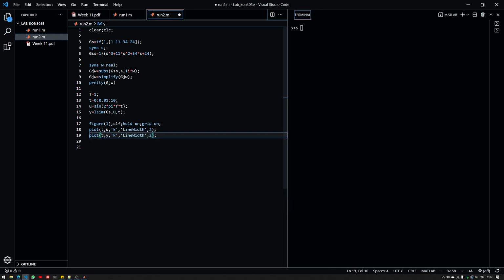So most of the time we use step functions and maybe impulse functions or ramp functions to examine a system's performance. For most of the time our applications require step-like inputs, therefore we examine that. But it is not really restricted to that. We might use a frequency range of inputs and try to design our system accordingly.